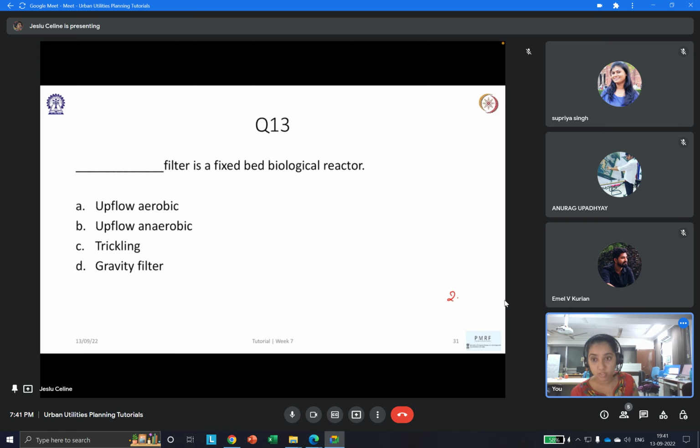Fine. So next question. Dash filter is a fixed bed biological reactor. Upflow anaerobic. Okay, right. Upflow anaerobic. Let's see, why not others? What is an upflow aerobic filter? Does such a filter exist? In sanitation, we're mainly not using such a filter. Upflow aerobic filter, we do not use. It's always an upflow anaerobic filter because there is no oxygen involved over there. It's an anaerobic process which is happening.